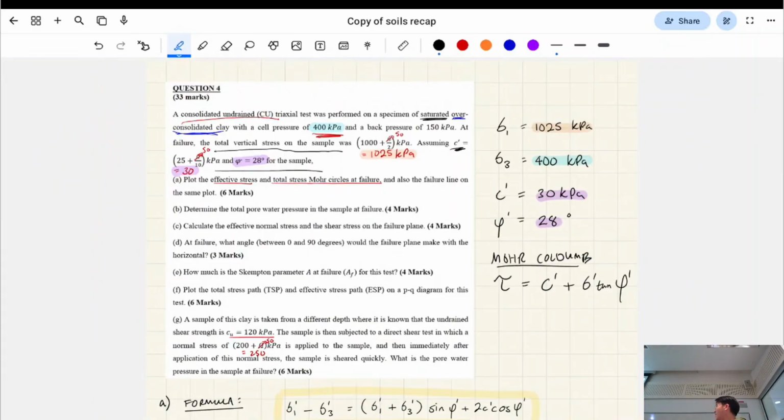If I had a heavy painting or a poster that I put onto this wall, and I put a bit of duct tape to hold it up, it's going to fail in shear if the painting's too heavy, right? Shearing is what happens with soil, essentially. You have two surfaces and they slip against each other. You're going to see when you look at slope stability as well,